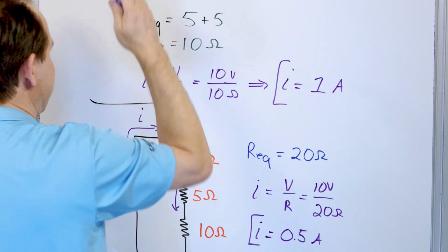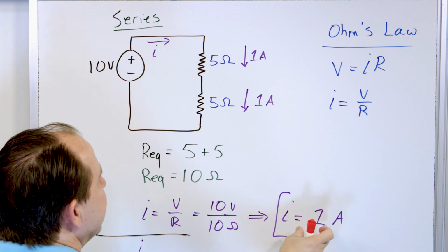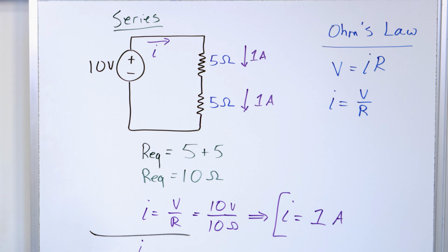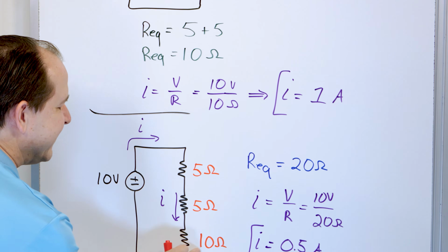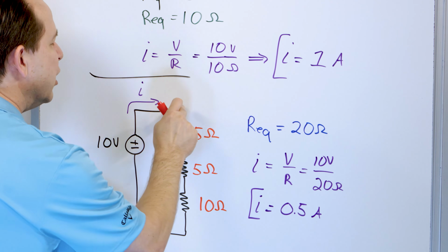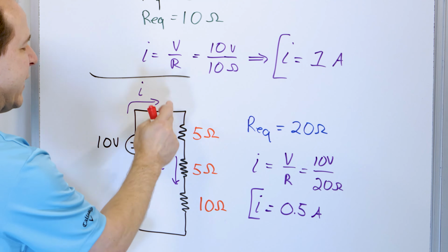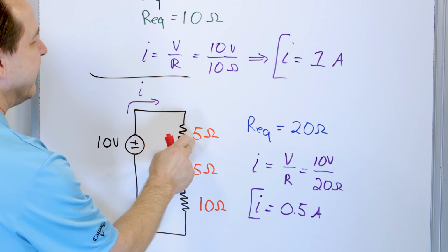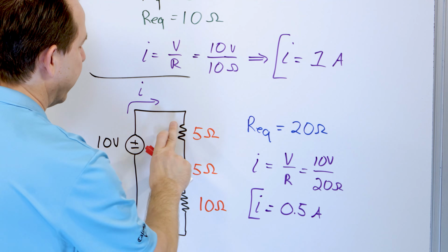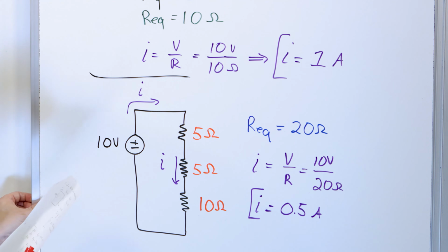And if these were light bulbs instead of resistors, right? If this were a light bulb and a light bulb, then this current would be causing them to be illuminated with a certain amount of illumination. As soon as we added another light bulb, let's say this light bulb had a higher internal resistance, the current would be lower, much lower, actually reduced by half through all 3 of them. It's the same current through all 3, and so that means these 2 bulbs, I should say, would be dimmer as compared to the original because there's less current flowing through them.